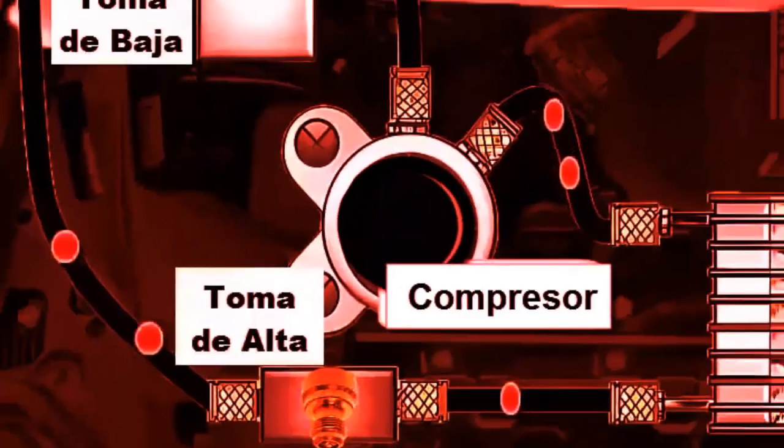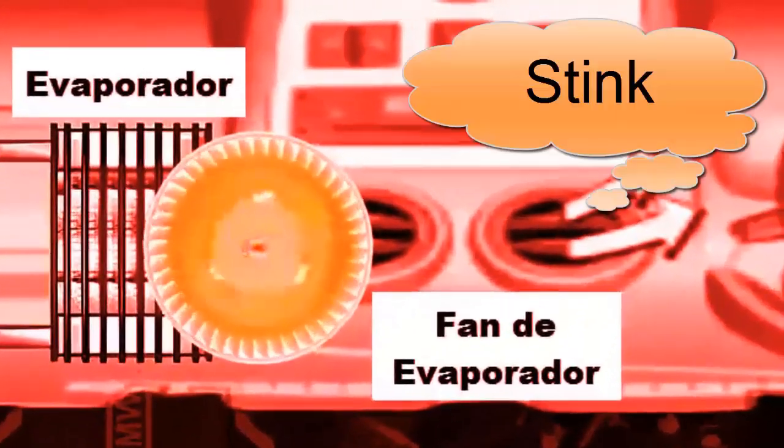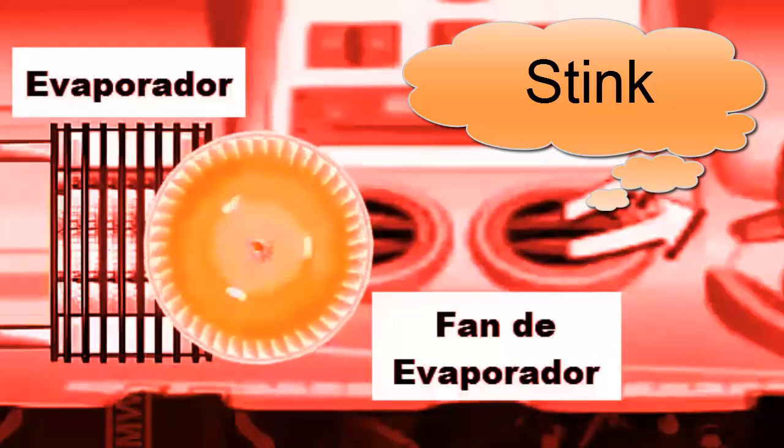6. Strange odor when turning on the automotive air conditioning. An odor may indicate moisture or the presence of oil in the system's interior coil or evaporator, possibly due to a refrigerant leak.